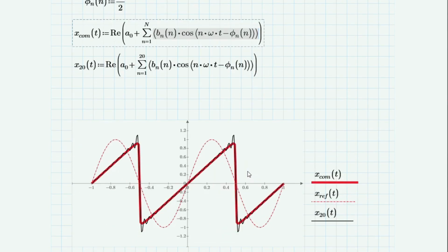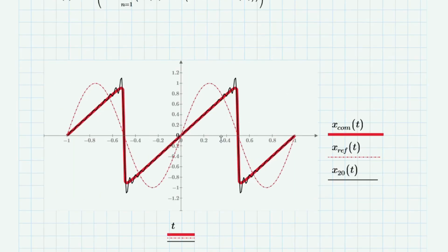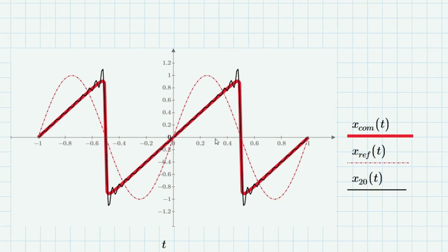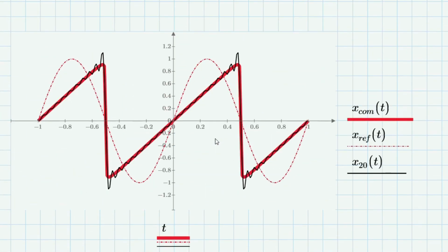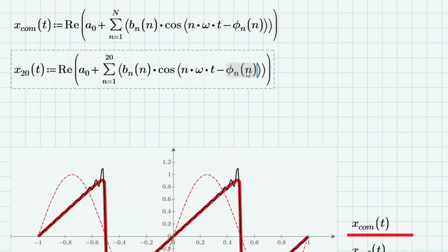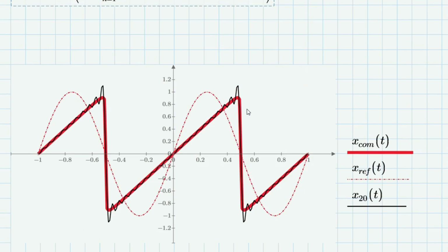The graphs here highlight the phase spectrum, showing how each harmonic is precisely timed to lag or lead the fundamental frequency. By adjusting these phase values, we can see exactly how the timing of different frequencies builds the steepness of the linear ramp. This is the most practical form for analyzing how hardware circuits introduce delay.